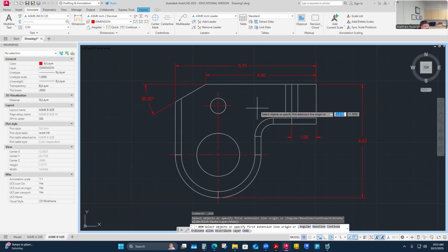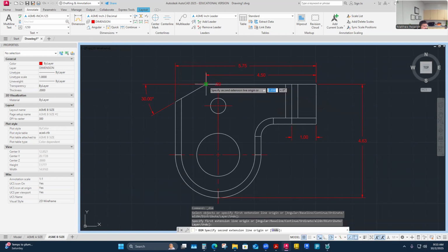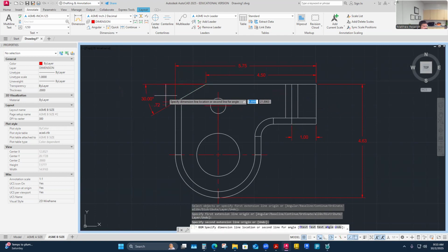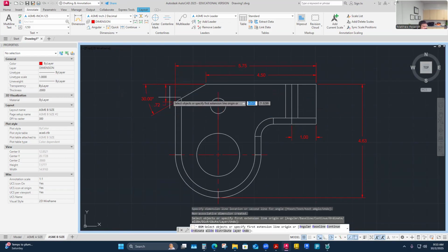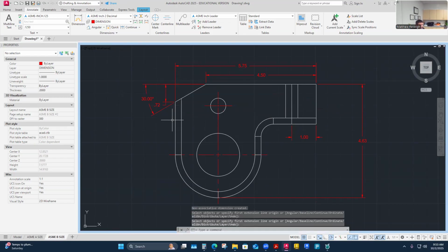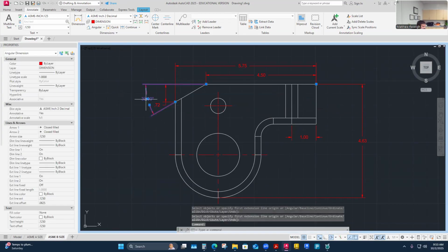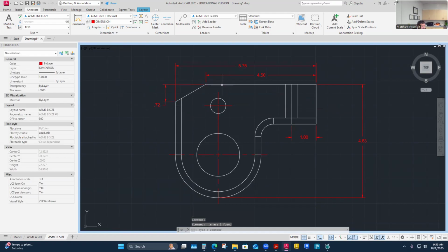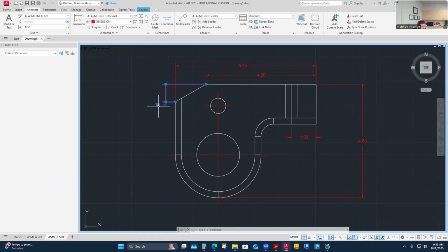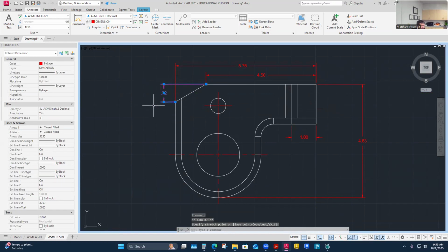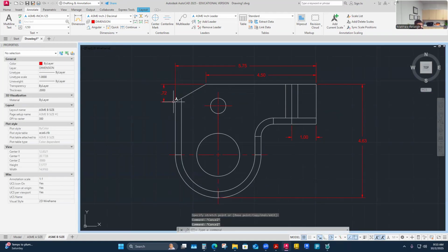So with that miter, I've defined two of the points, and now I need to define those in the Y direction. I would do that up here too. It would be this dimension from here to here, but totally vertical, this way. It's 0.72. It's not anything that would probably be on the drawing, but I like this better than maybe this. This is good. This might be better. This is a datum. I've established it from here, pulling off that back side, and so I'm using this to my advantage too. I'm pulling this dimension off that back side, so I'm not establishing something new. I wouldn't want to pull that from here to there and put it in here. I like this better.